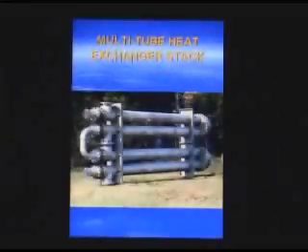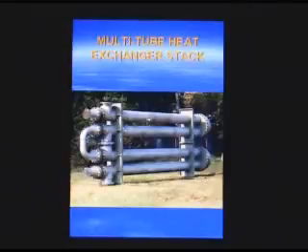Here's an example of an all stainless steel hairpin exchanger. This is actually built for a TEG gas dehydration package that was designed on a component by component basis rather than having the TEG supplier include these as part of his package. If any structural people are here, this one saddle is fixed, it's welded to the shell. A back saddle is sliding, so it can be slid to accommodate just about any foundation that you'd like.